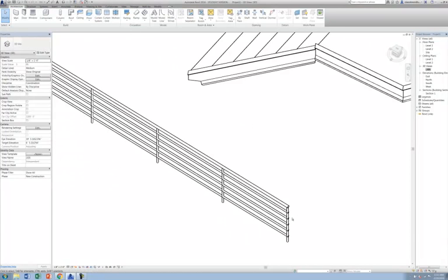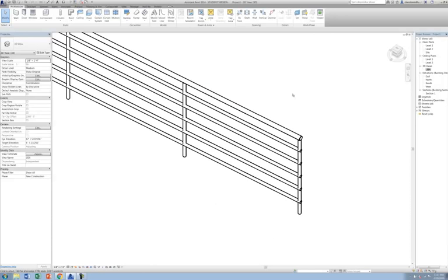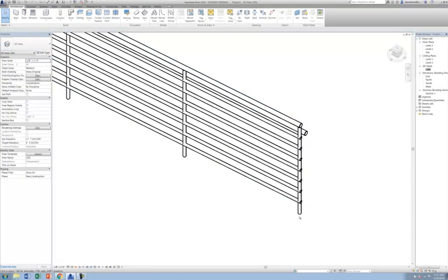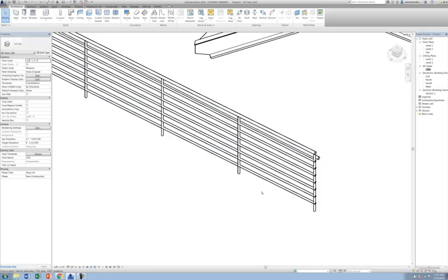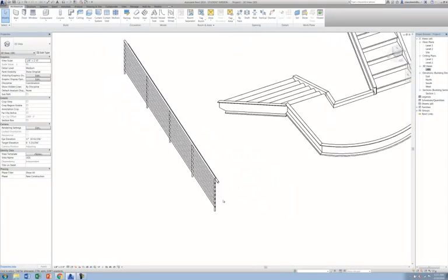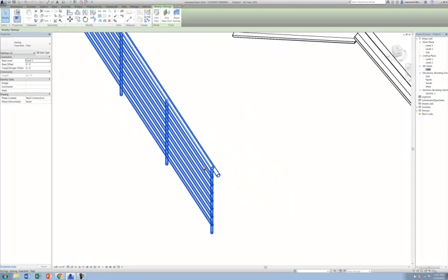You can see by default, when I've selected handrail, this is a condition where you're not on a staircase, but you're on some kind of a landing. There's no guardrail there. The difference between a guardrail and a handrail is that a guardrail is going to be taller, 42 inches, and it's going to have a handle at 36 inches for people to get around. So on sloped ramps and so forth, you're going to have this condition where people have the ability to grab hold of the handrail.